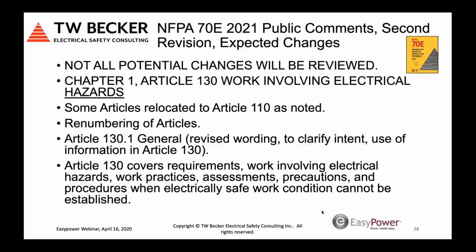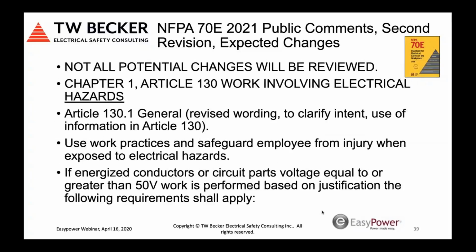So Article 130 covers requirements for work involving electrical hazards, work practices, assessments, precautions, and procedures when an electrically safe work condition cannot be established. It then says we want to use work practice and safeguard employee from injury when exposed to electrical hazards. If the energized conductor circuit parts are equal to or greater than 50 volts, we have that as 30 volts in Canada, so there's another difference. It's based on justification, and then the following requirements shall apply.